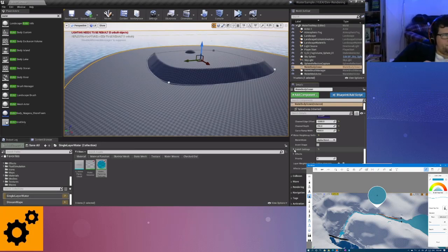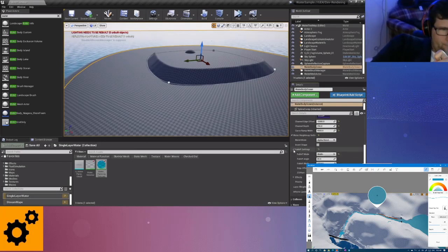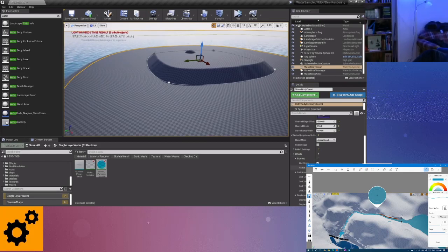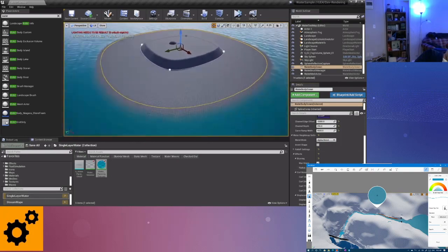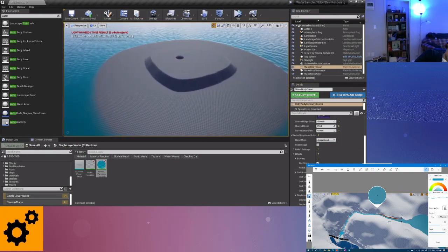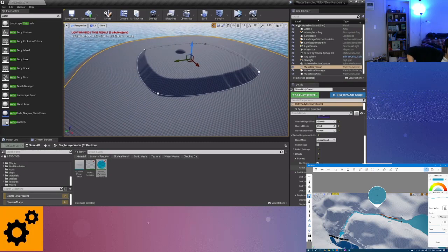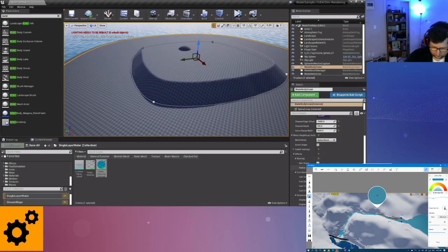And below the basic fall off settings for things like width and angle, there are these effects areas. There's a little bit of blurring because right now these shapes are actually generated on the distance field using jump flooding. So that process, when it's not done at a super high resolution, can pick up a little bit of aliasing artifacts. If I turn off blurring, it's on by default at 2, and that pretty much fixes it. But you can adjust it as needed to smooth out the result. But you'll notice that that's blurring the actual distance field result, not the height result. So no matter how blurry I set that, it's not going to blur this top edge.